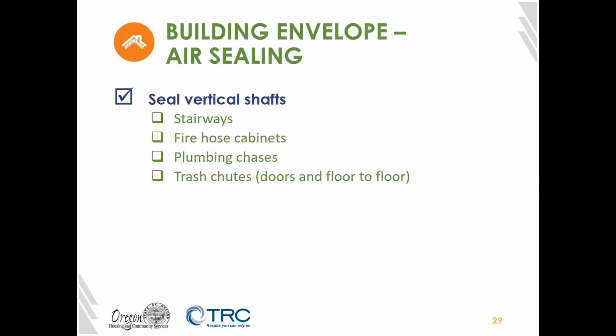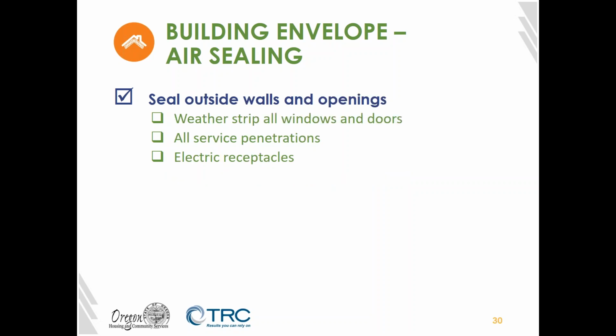We need to seal the doors and also seal those floor to floor so we don't just have a big opening around the trash chute itself. Obviously inside the trash chute will be open, but the surrounding area that it's in, you want to seal that at each floor to reduce air leakage.